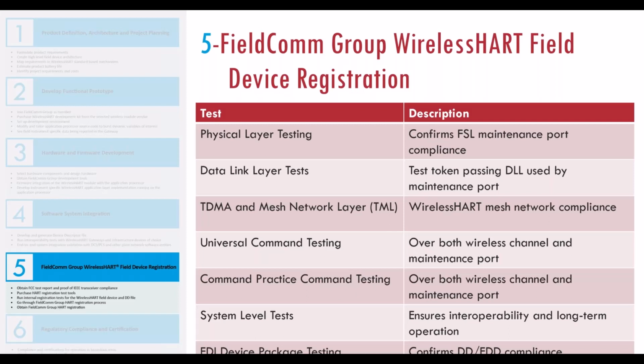Now, these tests are designed to ensure long-term operation interoperability. And the FieldComm also offers these tests separately from the actual certification process. And I would highly recommend that you do use their services because it is a long-term test. If I recall correctly, it takes a few weeks. They'll really leave the instrument connected to the test system and ensure that your instrument is also reliable and fully operational for a longer duration. And then along with your field instrument, you will also submit your EDD file.